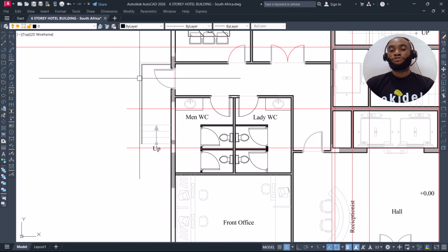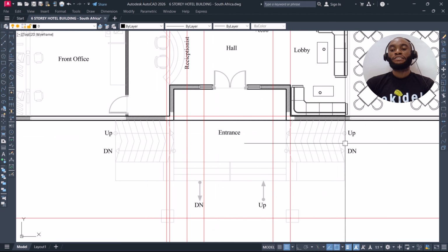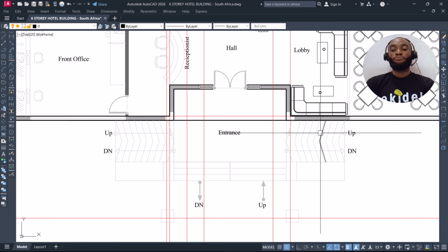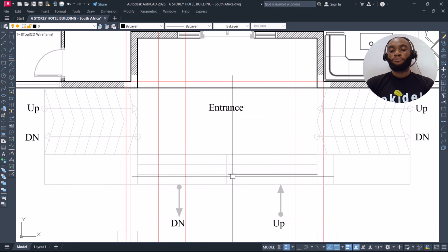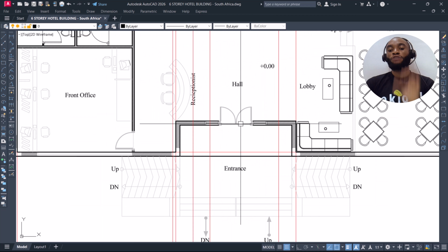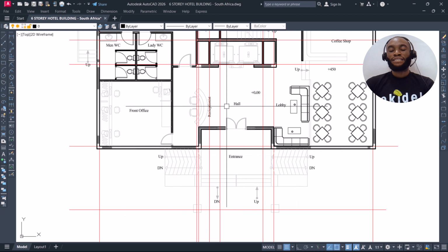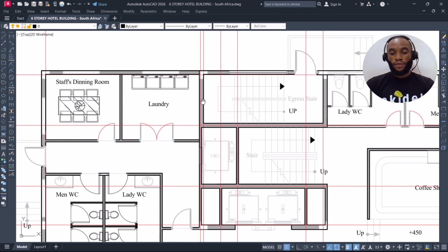So these are not structural staircases, and you can see that we have a ramp here that will lead to an entrance. These are not structurally designed ramps, so we can use mass concrete to get this ramp, using our wire mesh for reinforcement. Also, this is also a step to enter. So these are not structural members. We are only focusing on the structural members of this particular building. Okay, that is fine.